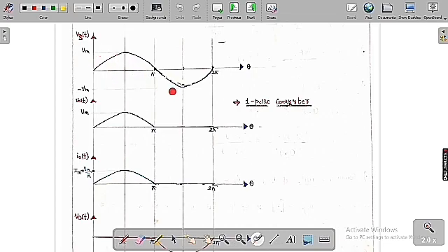Now let us draw the graphs of this one. Let me assume the source voltage is a sinusoidal voltage having a peak value of Vm and minus Vm. So one time period is 2 pi, so half time period is pi, with respect to theta that I am going to take here. And here from 0 to pi we can say that the supply voltage is greater than 0.